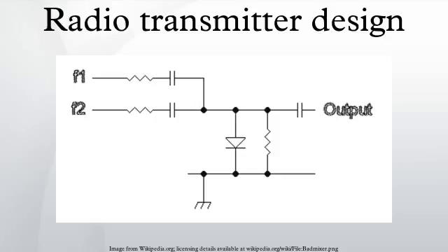Removal of harmonics with filters. In addition to the good design of the amplifier stages, the transmitter's output should be filtered with a low-pass filter to reduce the level of the harmonics. Typically the input and output are interchangeable and matched to 50 ohms. Inductance and capacity values will vary with frequency. Many transmitters switch in a suitable filter for the frequency band being used. The filter will pass the desired frequency and reduce all harmonics to acceptable levels.